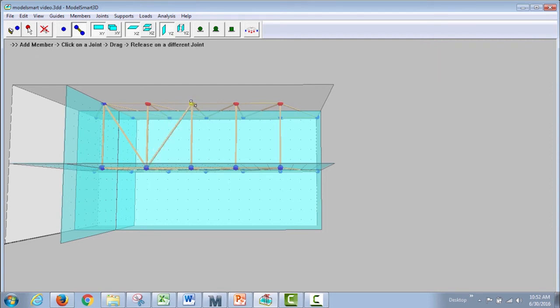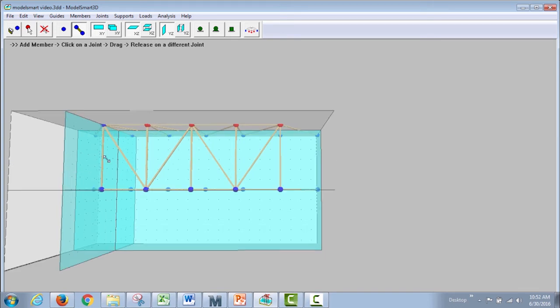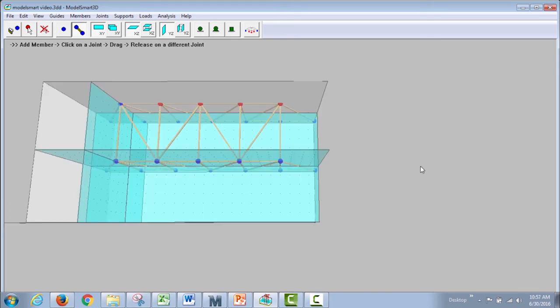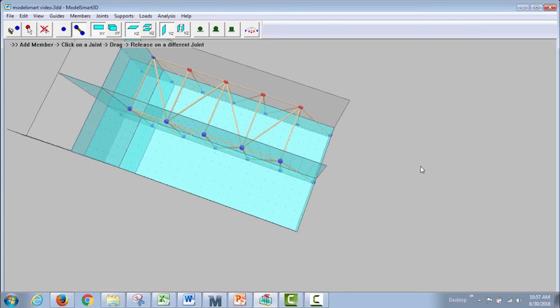This will prevent your two sides of the truss from distorting horizontally relative to one another. Along the bottom of your bridge, this isn't really so big of an issue because the tension force along your bottom chord members will help to prevent this distortion relative to the two sides.